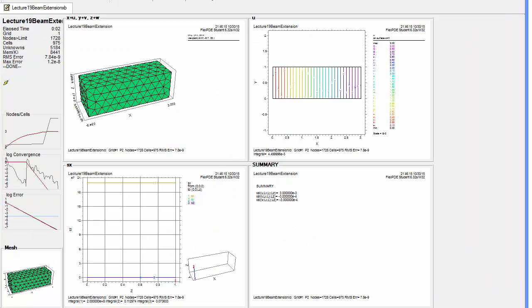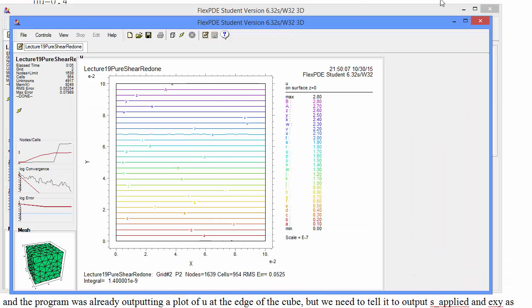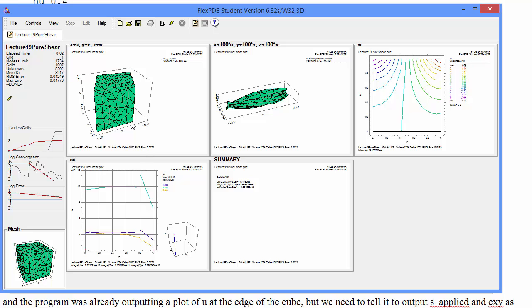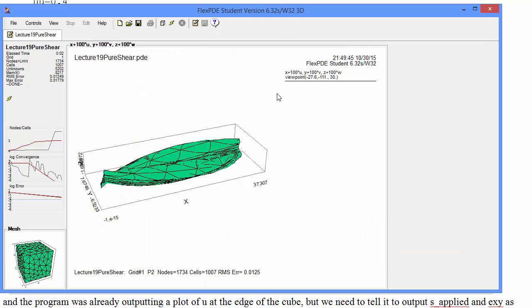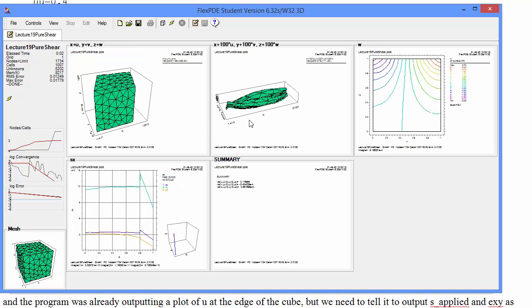So, don't get discouraged if at first you end up with something going wrong here. It's probably to do with what's going on with your boundary conditions, what size you set things to. If you try and magnify the stress, you may find that meshes are badly folded, and it's showing you the wrong kind of displacement there. So just double check things, be careful with what you've changed, go back to code that worked, and don't give up.